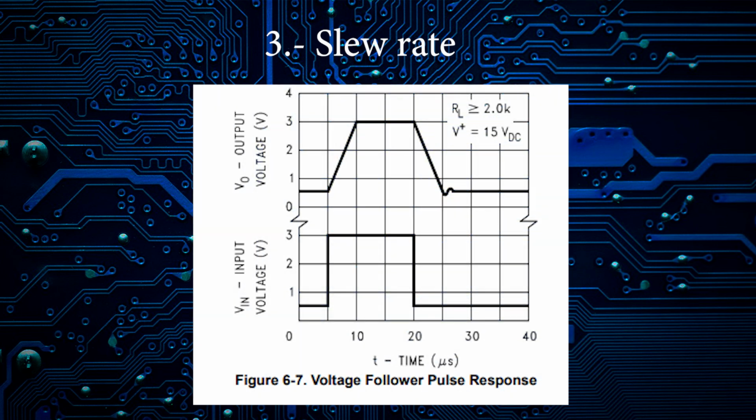The slew rate in op-amps affects us in many ways, but here we're going to look at it specifically with a square wave signal, where we can best appreciate it. In many cases, we will need to amplify square wave signals, whether for PWM or other types of digital signals. The slew rate then affects the waveform of the signal, which can be even more problematic at high frequencies. Let's look at a direct case.